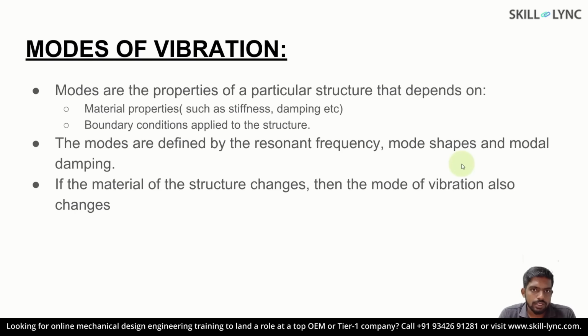The displacements produced at the natural frequency of the material are referred to as mode shapes, and the mode shape can vary from material to material. That is, if you have a material producing a mode shape at a given frequency, the mode shape created by a different material will be different. Also, if a material produces a set of mode shapes at a specified frequency, the same material will produce a different set of modes if the loading conditions are changed. This will make more sense if we just look at a simulation to understand this phenomenon.